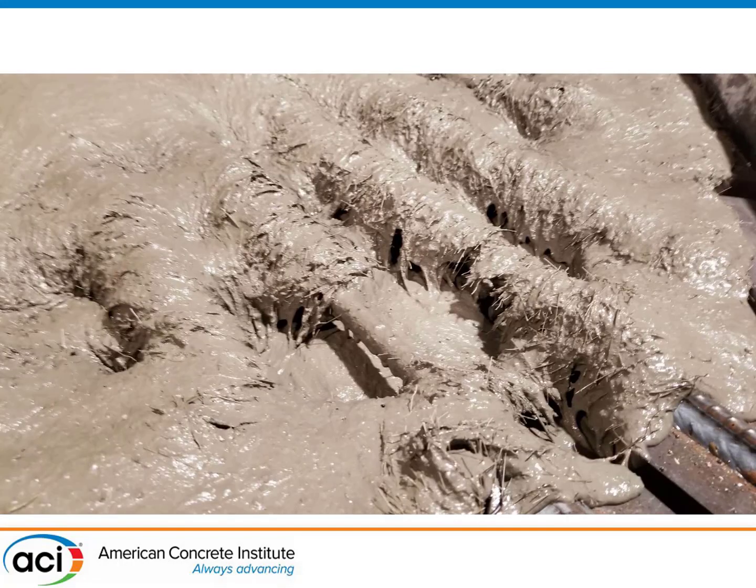This is a zoomed-in view of the fibers, basically giving us some issues of fiber alignment around the reinforcement. But in the end, after the failure, we did not see any evidence that the fibers at the crack had any non-randomness. So they appeared to be random and in good shape, and the casting went quite well.